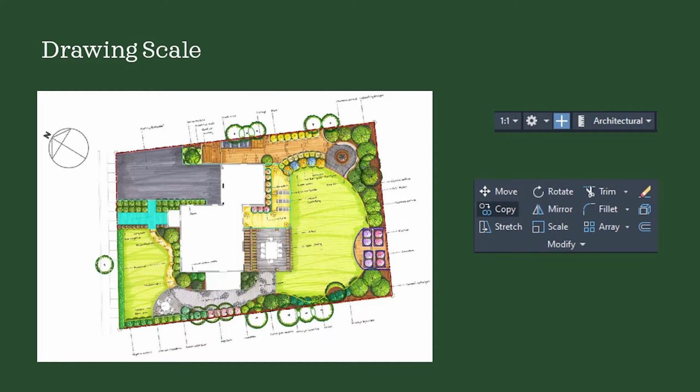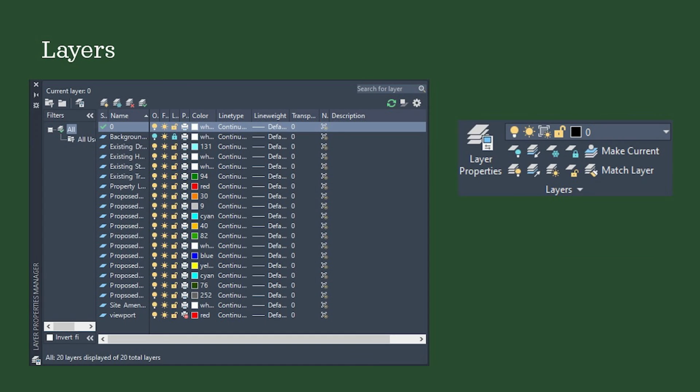The background image was scaled by drawing a reference line of a known distance and scaling the rest of the drawing around that. The reference point in this design was the doorway, which had a distance of 3 feet. After the line is set to the right distance, the rest of the drawing scales proportionally and can be checked with the measure tool. This tool was also used to scale the imported blocks that represented various pieces of furniture.